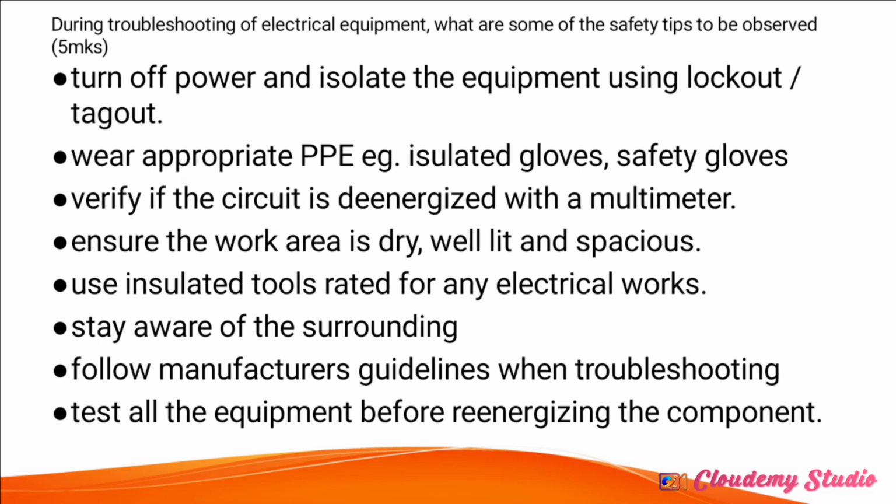So you have to test using the multimeter to confirm that once you have turned off the power and isolated the system from the main source of power, the components that you are trying to troubleshoot do not have any energy in them.